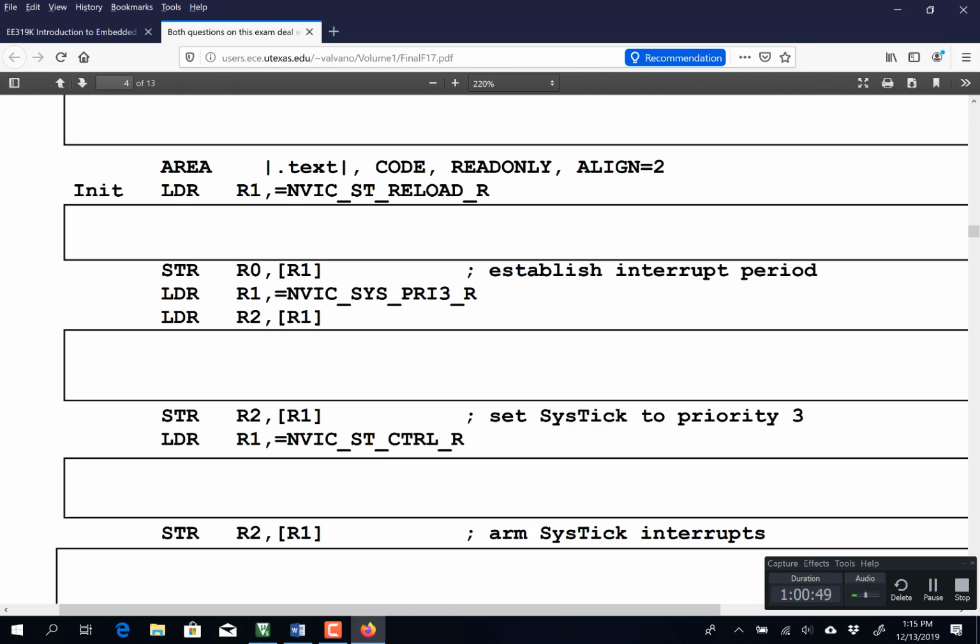You got to read it. You got to clear the top 3 bits. You got to set the top 3 bits and store it back. But I've obviously already read it for you, and I've already stored it. So in this case here, you're going to AND it, clear the top 3 bits, OR it with the priority 1, and it will store back. And right there's a 7.